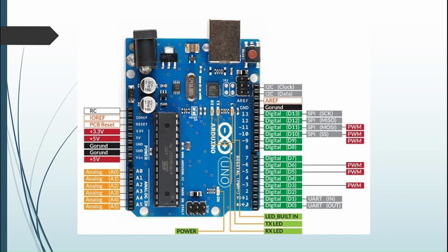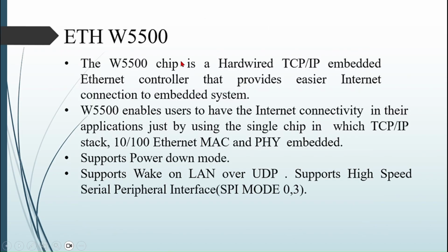This is an overall view of our Arduino. This is the USB power connector. This is a 12 volt power supply connector to our Arduino. This is the main controller of our Arduino UNO. These are the analog pins and the power pins. These are our digital pins used to connect our Arduino to digital signals. This is the indicator that tells us the Arduino is on, and these are different LEDs. This is the reset button of our Arduino.